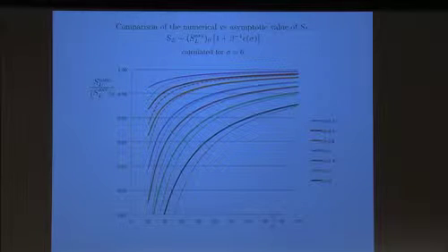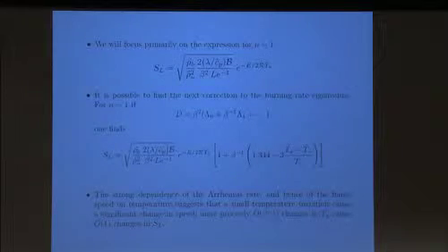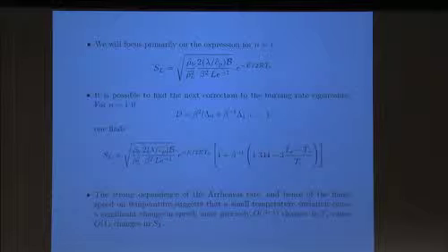So with that said, let's make the last point written here: the flame speed shows a very strong dependence on the Arrhenius rate, in particular on this exponential, because any slight change in the adiabatic temperature makes a significant change in the flame speed. It's enough to change TA by a quantity which is like 1 over beta. In other words, a small change of maybe a few hundred Kelvin makes a significant change in the flame speed. And that's what this expression, in fact, shows.